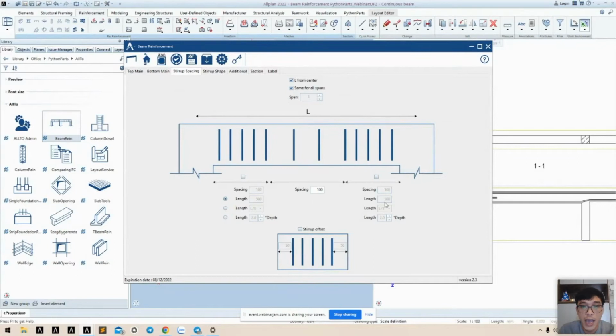And as you can see, we have the ability to create the stirrup with 3 placements, maximum 3 placements of stirrup, when we tick this checkbox. And here we have a number box to define the spacing for each placement. Example, 15 centimeter. Yeah. 25 centimeter here.